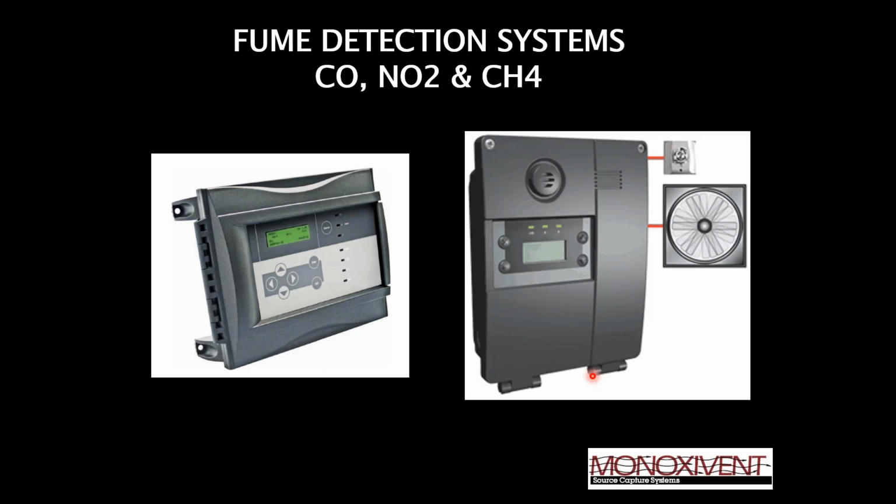All right, so now fume detection systems. Not every vehicle exhaust application lends itself to source capture. As an example of that, I always use a public parking garage, right? There's a lot of cars going in or out or idling while they're in there, but there's no way you'd ever get them to connect to a hose reel or an underground system or an overhead system.